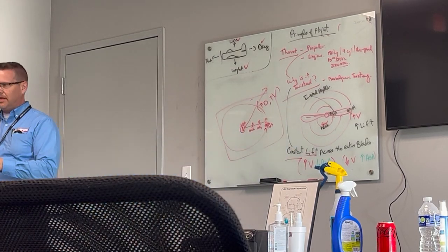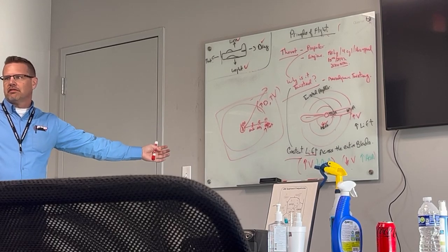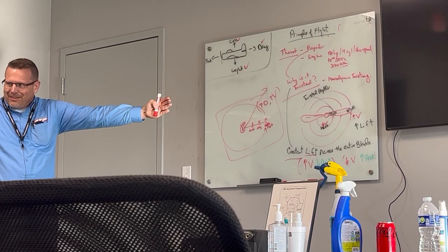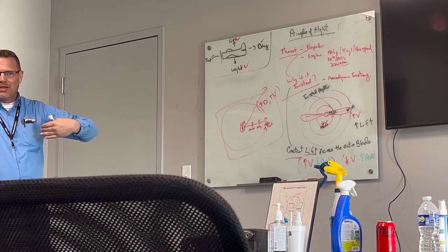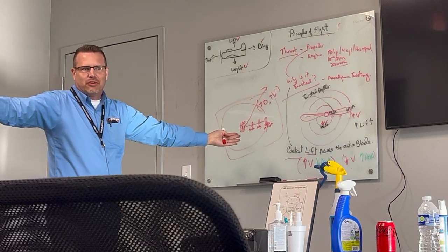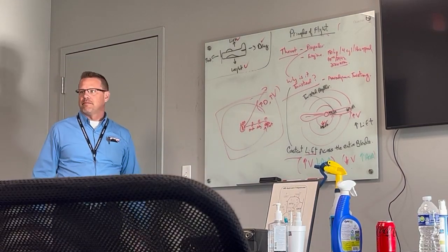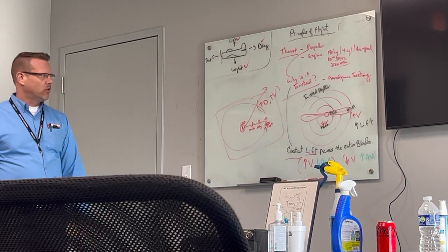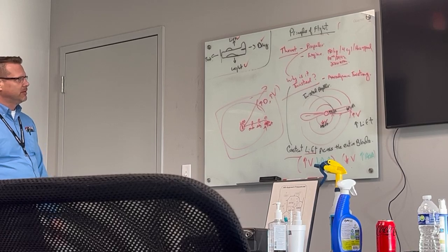Otherwise, the outside of the blades, the tips, are going to create a lot of lift. And so if we were spinning the blade really fast, the blades would flex while we're flying. The inside wouldn't be producing much lift, and the outside would be producing a ton of lift, so the blade would want to bend forward on the outside from all the thrust that it's producing.